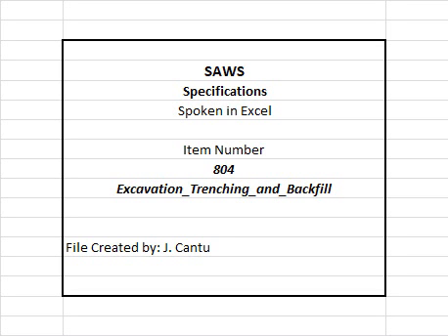E. The frequency and location of testing shall be determined solely by the SAWS. Or at a minimum tests will be done at location points randomly selected as indicated by the inspector/test administrator, per each 18, first lift from bottom, and 12-inch loose lift per 100 linear feet, at a probe depth of 6 inches. 1 per lift per 100 feet. F. The owner may test any lift of fill at any time, location, or elevation.